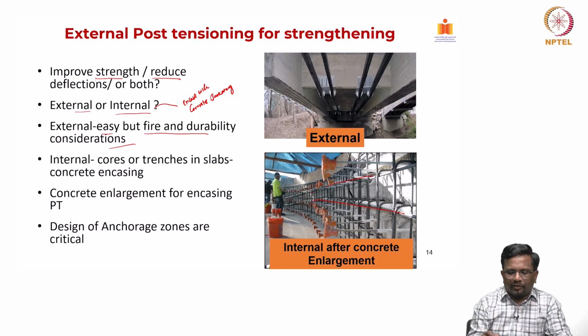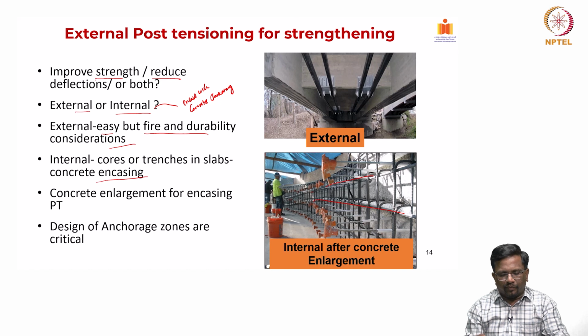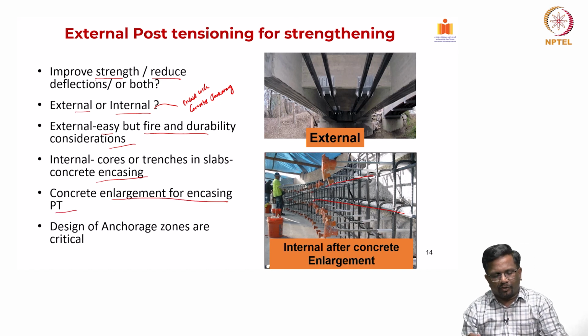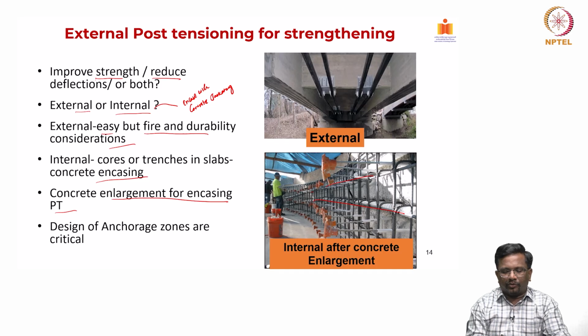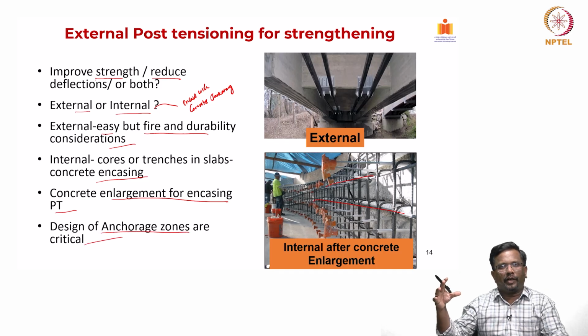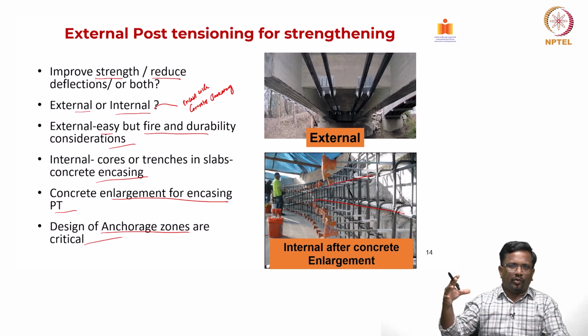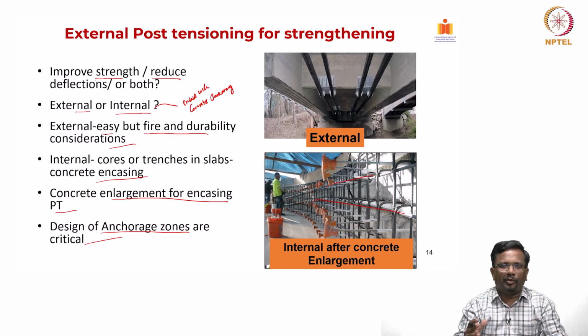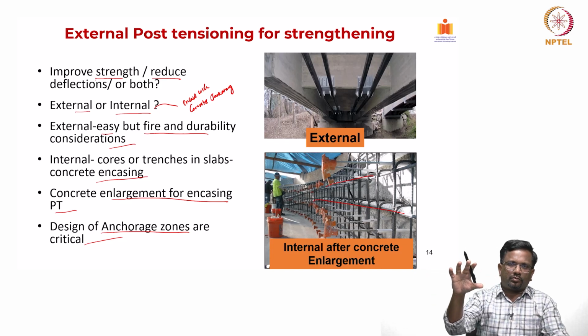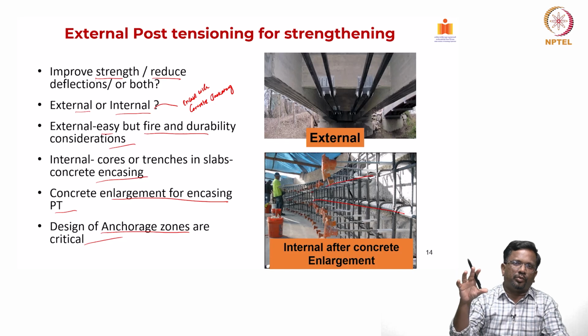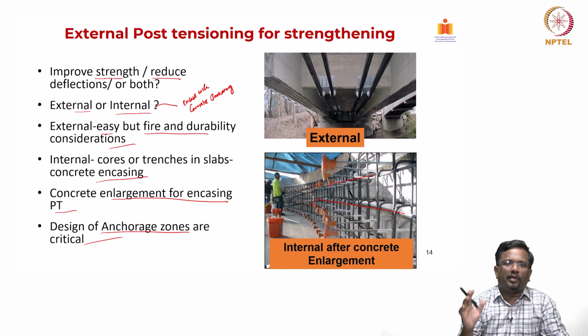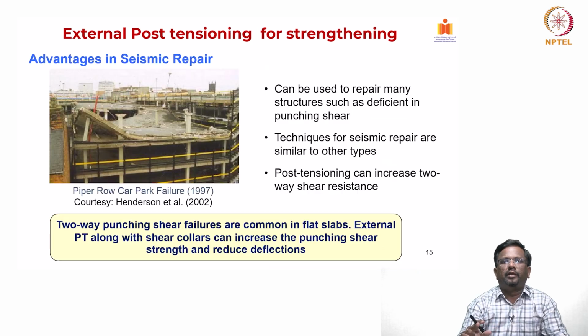Internal options are cores or trenches in the slabs, or concrete encasing like what we have seen in the picture. Now, concrete enlargement for encasing the PT also is possible, and design of anchorage zones is very, very critical, because now we are adding a PT force by reacting against the member itself. I have to choose the locations where I am putting these anchors, and at those anchor locations you will have heavy stress concentration. So, we need to design those anchor zones very carefully.